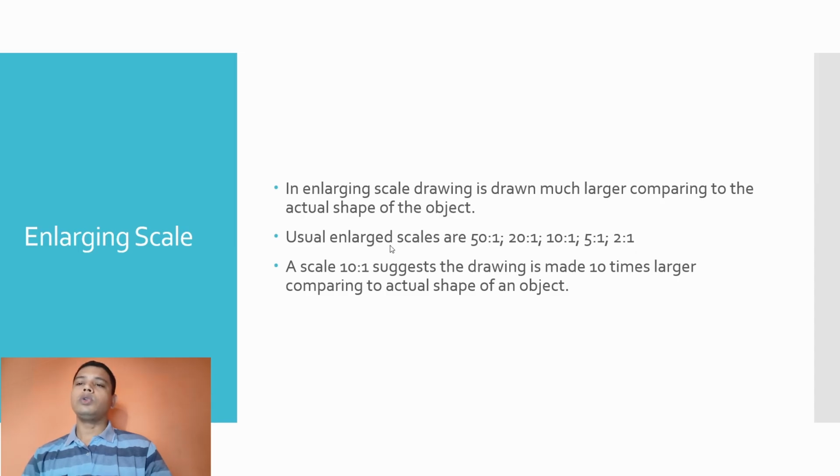I suggest you also keep a note of these standard scales, because sometimes you have to show a sectional portion of any assembly or any part of an object in a much enlarged view, or in a wholesome drawing you may have to show each and every part in a much enlarged view. Then you have to utilize these scales: 50:1, 20:1, 10:1, 5:1, 2:1, etc. I would suggest you keep a note of these scales. This is going to be very helpful in your standard drawing production process.